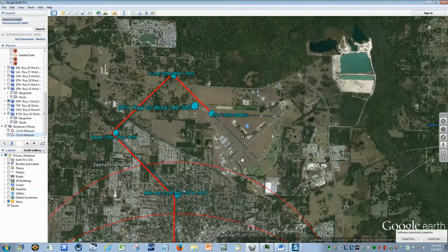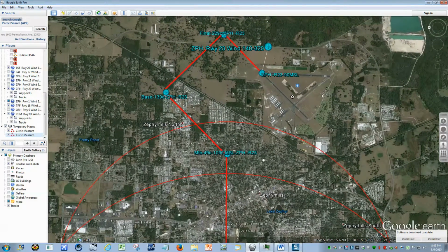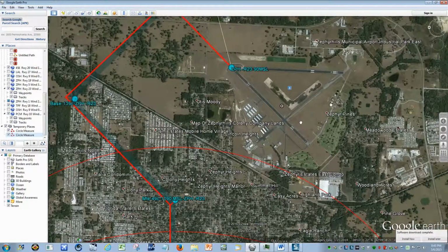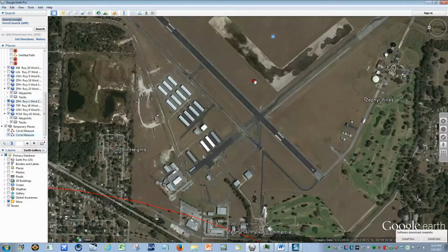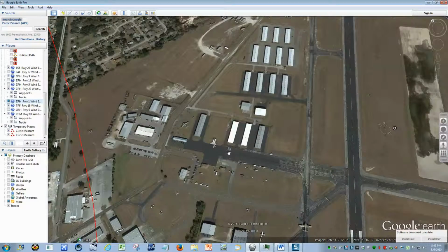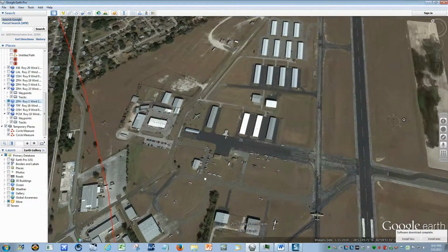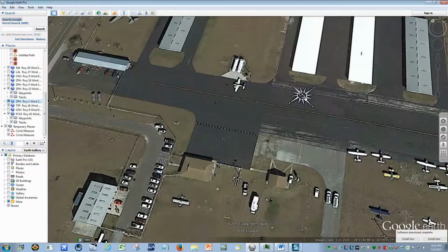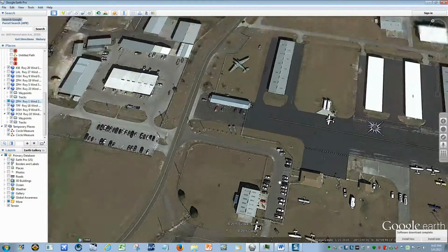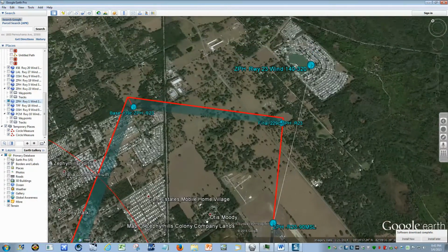Continuing the approach to the arrival airport, using the zoom and pan features enables identifying points of interest on the ground, such as nav aids, taxiways, tie-down ramps, fuel islands, FBOs, windsocks, airport access roads, restaurants, lodging, approach lighting systems, etc. A hovering information icon associated with the arrival procedure contains the procedure runway number and a 180-degree clockwise wind range for the selected runway.